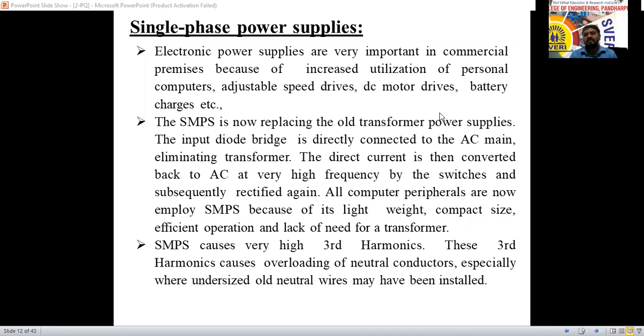That is the advantage in transmission systems, distribution systems and utility side. But considering harmonics, and efficiency in computers, the transformer is not small in size, it is not efficient, and there are so many conversions, so the cost increases. By considering all these things, we are going to use SMPS.